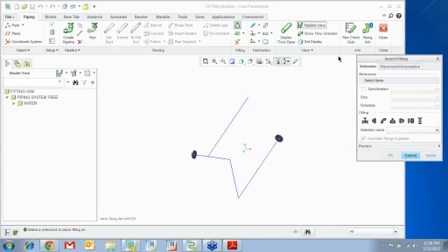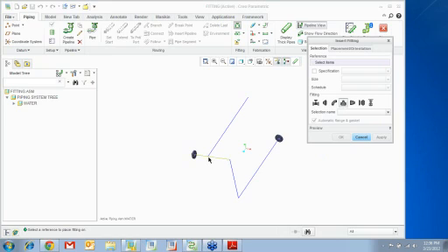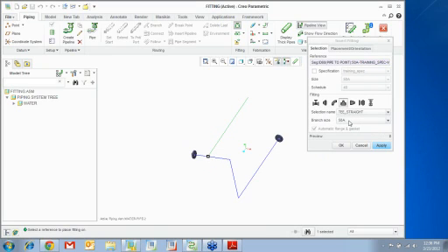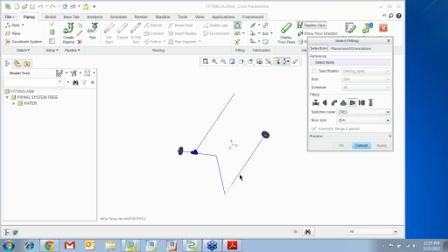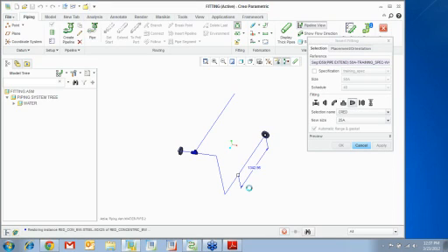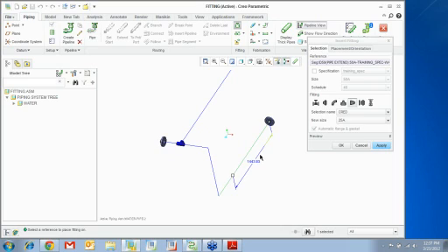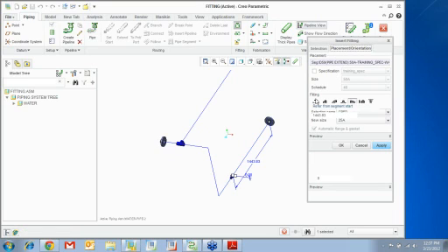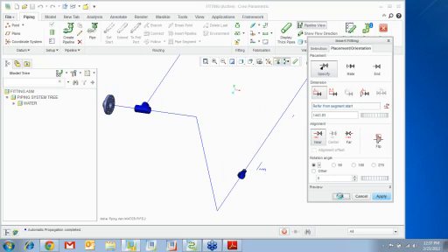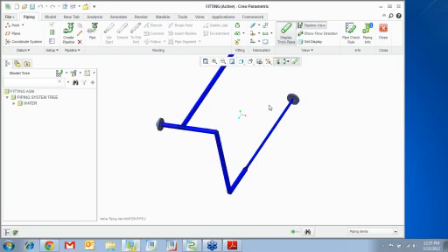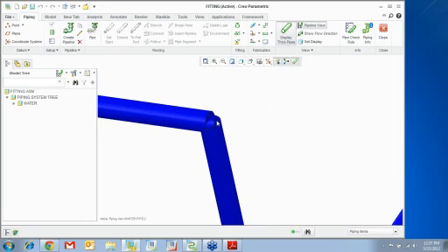Now, insert a fitting. All right. Now I want to stick in a T section right there. So notice it picks the size. Now these sizes, I can hit apply. Right? You can stick in a reducer if you want to. See that? And you can position it. And you can see the orientation of the reducer. You can flip it. You can rotate it 90 degrees. Wherever it's a circle, so it doesn't make a difference right now. Right? Now you can go look at thick pipes and you can see that.